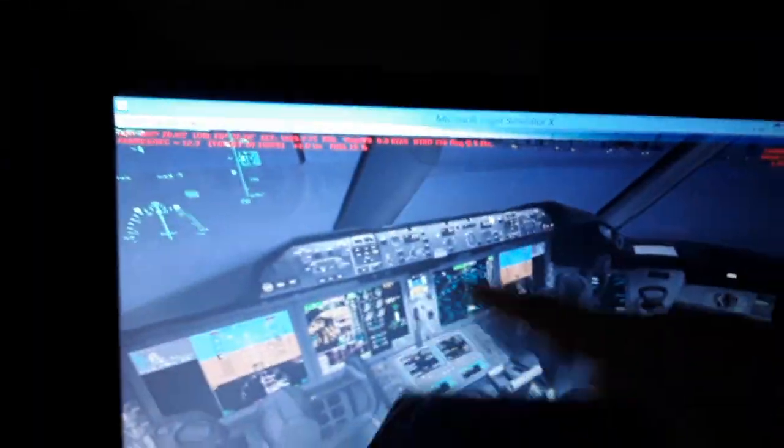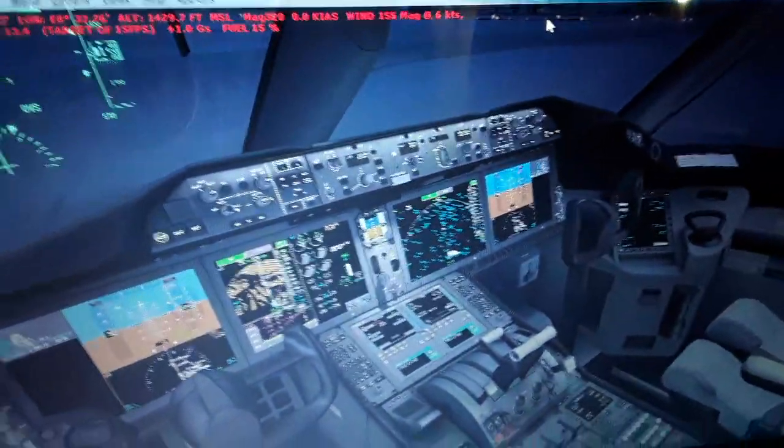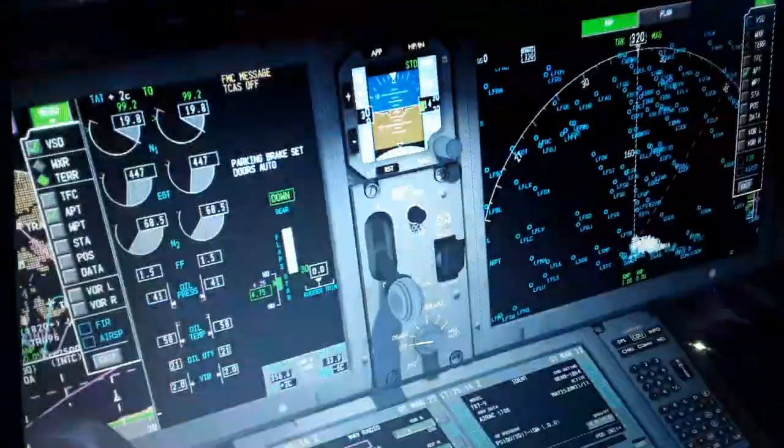We have the FADEC in the engines, the full authority digital electronic control computers, one per engine gearbox, with dual channel redundancy. One channel is in phase, the other takes over; it controls and monitors and displays all the engine functions. You see in the upper and lower EICAS engine indication and crew alerting system display the N1, which is the low speed spool, the low pressure compressor, of the turbofan engine, the exhaust gas temperature per engine, N2, which is the high speed spool, the high pressure compressor, of the turbofan engine, and fuel flow per engine per hour, in 1000 kilograms or pounds. So the pressure, the temperature, the quantity, and the vibration of the N2 states of the engine over here.